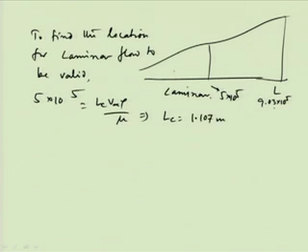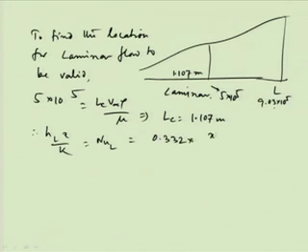So, for 1.107 meter it is laminar, and the rest is turbulent. So, what we can say is that h_L x by k, the Nusselt number in the laminar region, is equal to 0.332 into (x V infinity rho by mu) whole to the power half into Prandtl to the power 1/3.